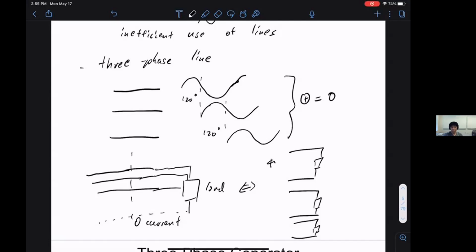No, it's not the load. The load doesn't care how many phase you have per se. The load is fine. If you have a 20-phase thing, I can probably make the load be 20-phase. But we're getting there. So if you have 4-phase or higher, turns out the system gets increasingly complicated. And the system is too complicated. And balancing things across 4 phases is very challenging. Okay, so 3-phase, we need to balance this, it's hard enough. 4-phase is very challenging. And you don't get much benefit when you have 4-phase.